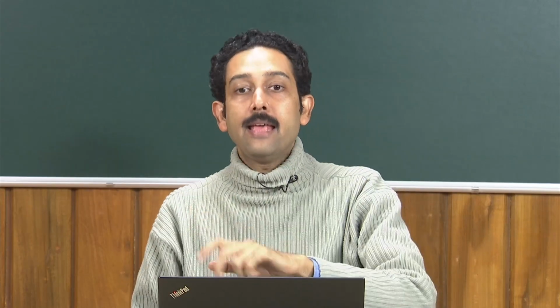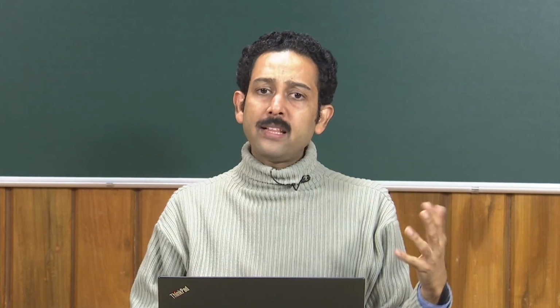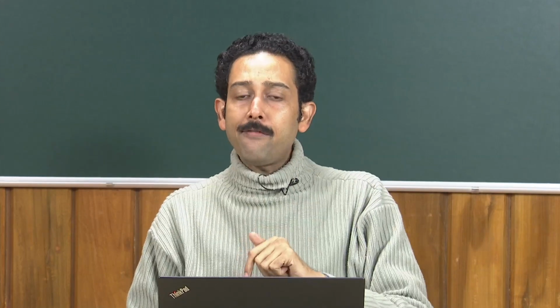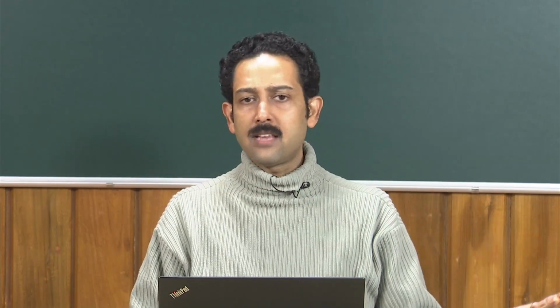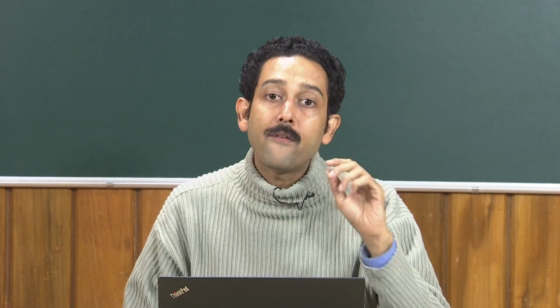Can it still be 1, and if it is still 1, what variable has to be 1, and so forth. Like if we want to say that these 2 BDDs, or these 2 functions, are not equivalent, but what if I make y equal to 0? For example, I assume that for a certain circuit or system, the y is always 0. Under that circumstance, do the 2 BDDs become equivalent? That is a very important operation in formal verification, which is called restrict.